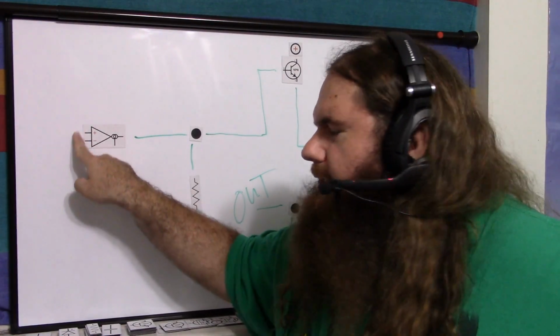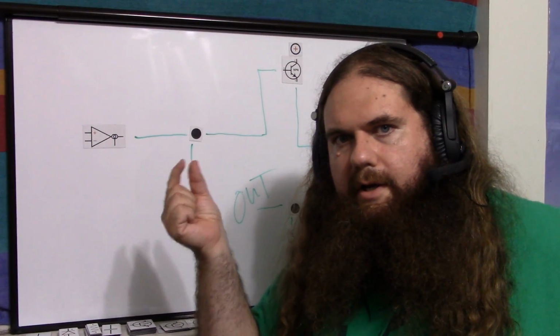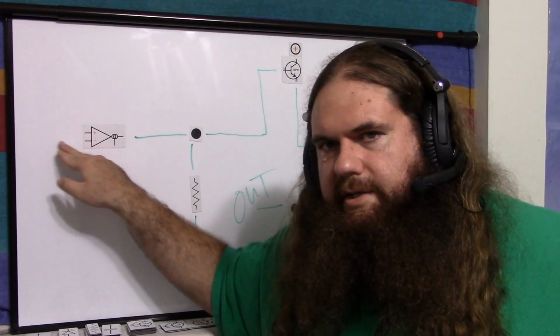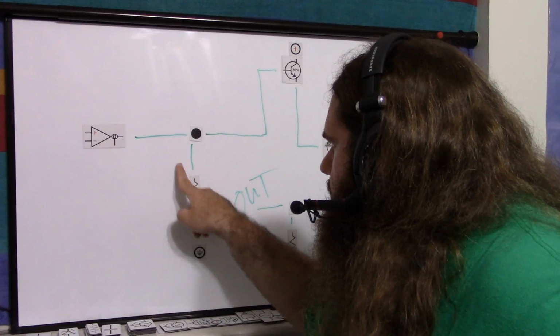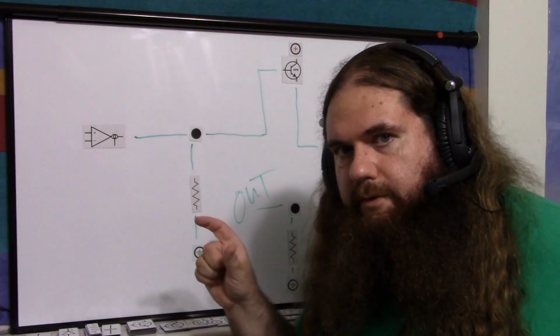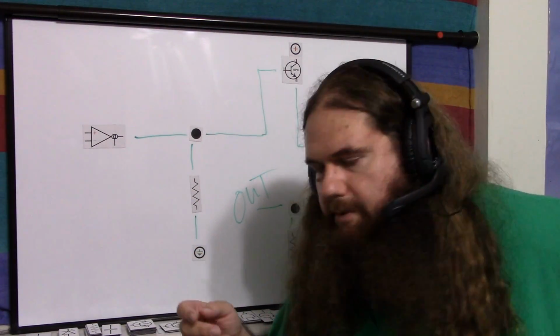But essentially, you just get your same differential input voltage, and your gain is set by a current, and then you have linearizing diodes, which gets a current, and your output is a current, which you can put across a load and you'll get a varying voltage for the same current, and then you can buffer it to actually use it in something. So let me know if my explanation was terrible.